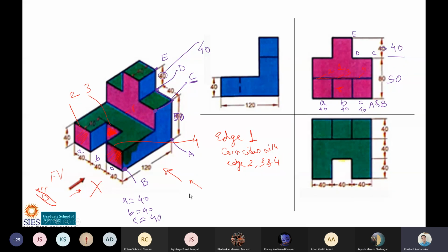Okay, now look at the object from this side. So this is giving us what? This is giving us the side view. So what will you see in the side view? It will start from here. See this one, this thing. So you can see a rotated L like this. So this rotated L is drawn here. And above this, this blue color will come. So this edge starting from point C and this edge starting from point D will coincide.